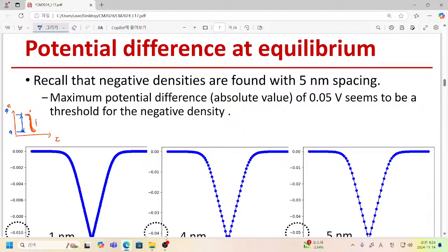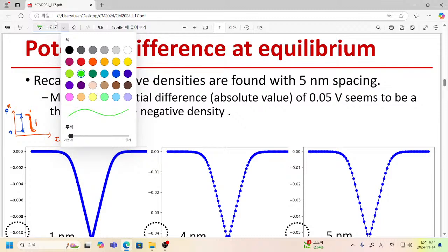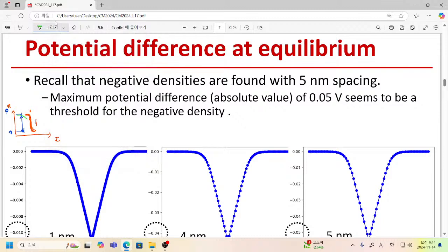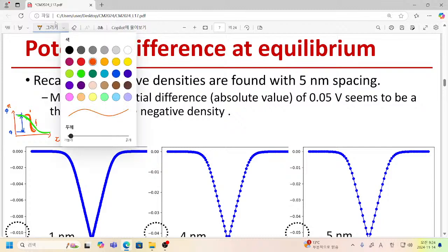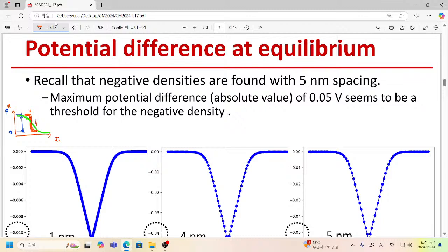So simply speaking, when we have this kind of thing and with the increased doping density, then if we have a much more moderate transition here previously with a relatively low doping density, but if we have a high doping density, now our transition becomes really sharp, and we can expect that the electric field in this depletion region can be increased significantly.